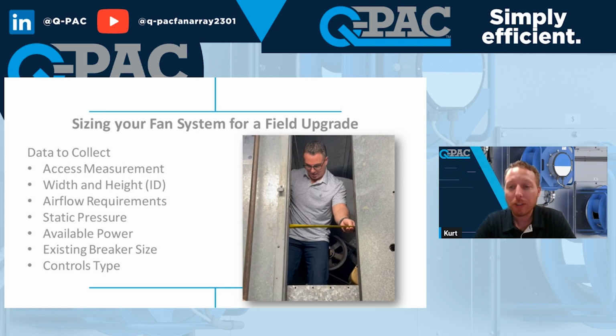All the components can be turned so they can go through a normal standard door, but depending on the height or the size of the air handler, our bulkheads can actually get up to 140 inches. So you want to make sure that if you bring in the components to the service elevator, they can fit the height of our bulkheads.